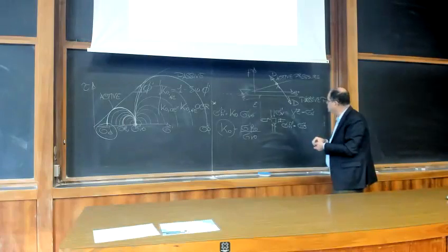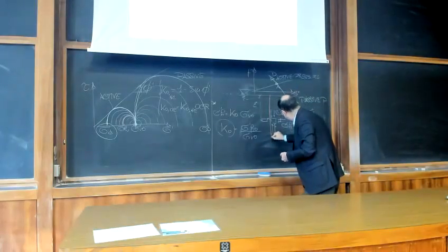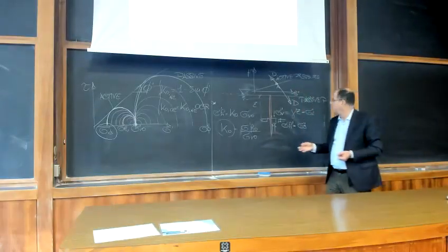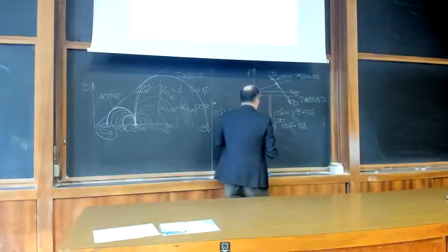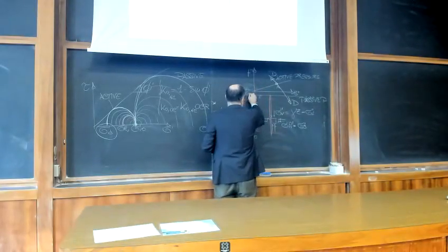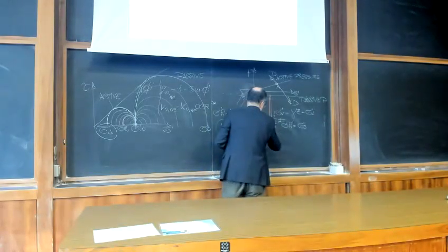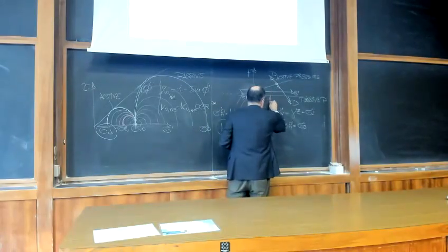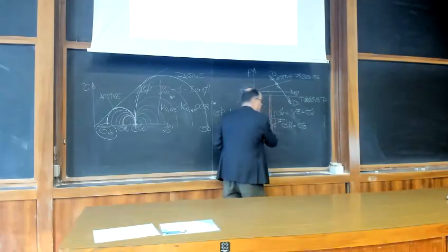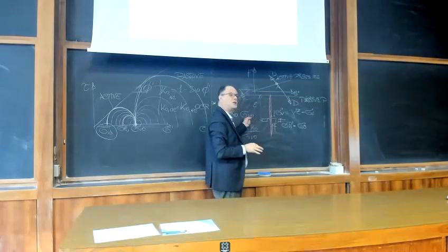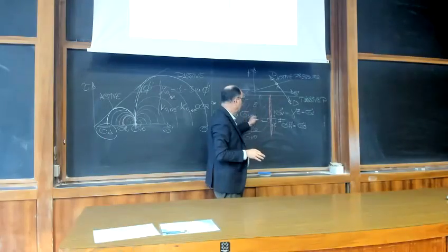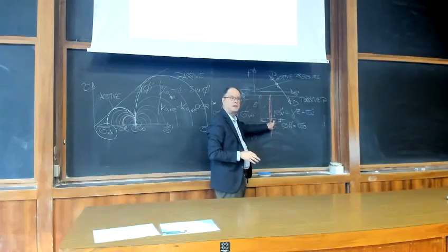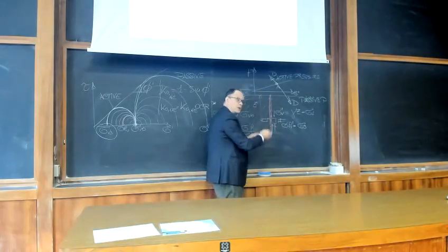So now let's assume that you remove this soil and you substitute it with an imaginary wall which is able to provide the same initial horizontal stress. Okay? So in this case, you have exactly the same stress state in this soil element, because you have just removed the soil but put a wall inside.